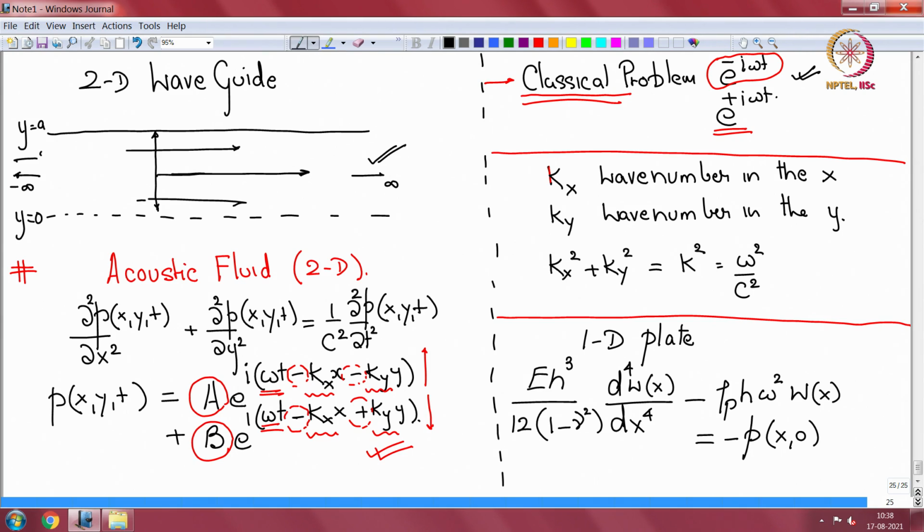Okay, so the time behavior has been removed because it's a linear system and every variable vibrates at omega, that has been removed. And so now, the y dependence, what I mean is the z dependence for the plate in the other direction, is not there, so it's just dependent on x. So I have written it accordingly. The time has been removed because it's harmonic.